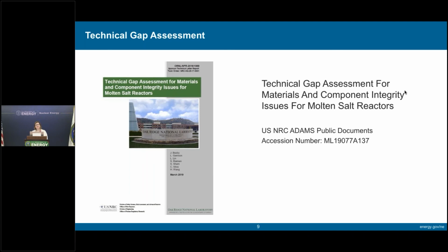Is the focus on alloy 709, or could it be? Again, I don't know, but alloy 709 definitely has a very high chrome content. Whether or not that is optimum for chloride salt application, I don't know. But that material definitely has a higher temperature performance than 316 stainless steel in terms of high temperature strengths like creep strength, etc. But I don't think we have too much information in terms of corrosion resistance. So that is part of what the proposers will have to put together: some logic in terms of why they propose certain classes of materials that they want to work on.